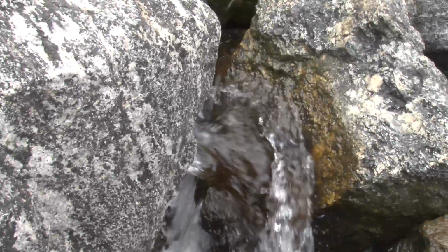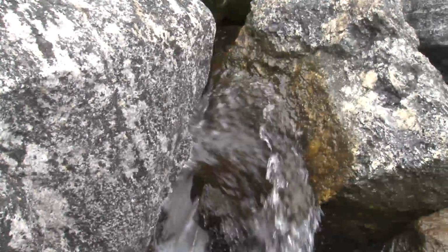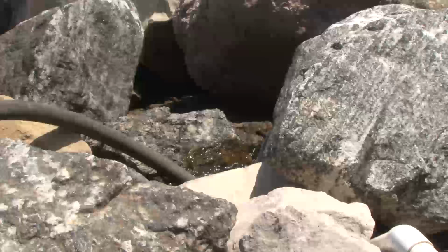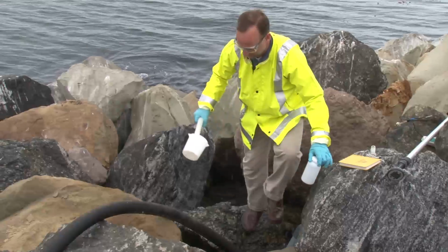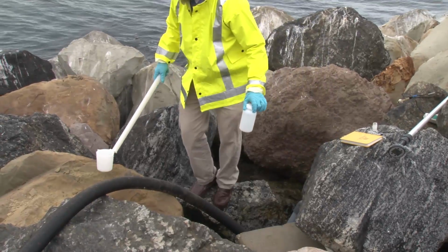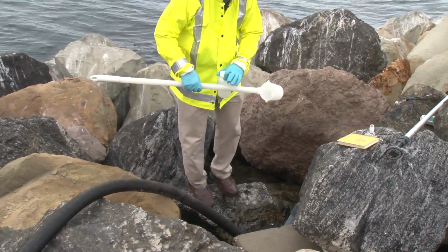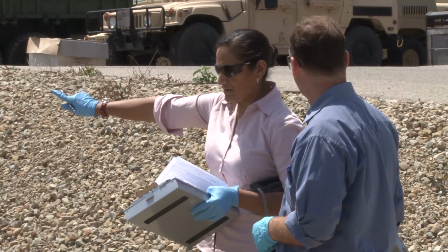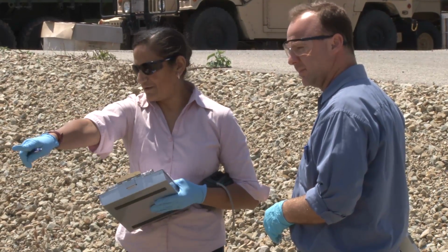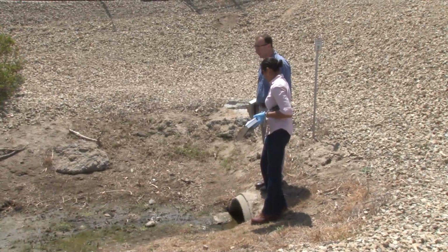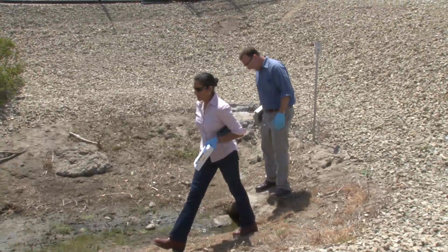During heavy storms, there are dangers from flash floods and from deep and fast-moving water. There are also special hazards associated with confined spaces, which could be a danger to storm sampling personnel. People taking these samples must be properly trained and must be aware of the potential hazards. It is highly recommended that sampling teams of at least 2 people perform these tasks. Doing so will reduce the risk of injury to personnel and make performing tasks easier.